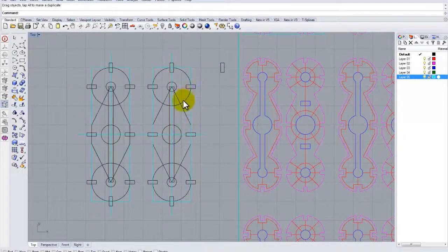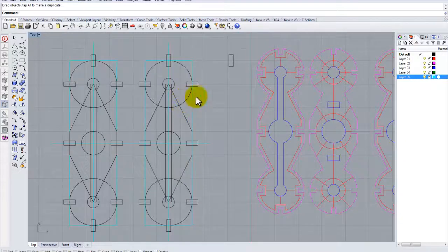But it's important, and it's a very good idea, that you take the time to measure your notch form before you cut these out. Now, you can put placeholders in there, and I'm going to show you how, if you needed to change your notch size, how you could really efficiently go in and change out your notch size once you know what your material thickness is. So don't let that stop you.